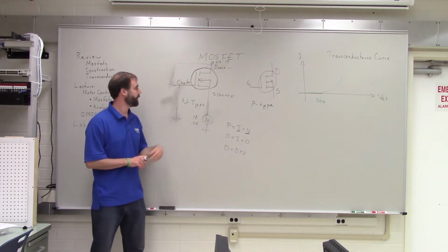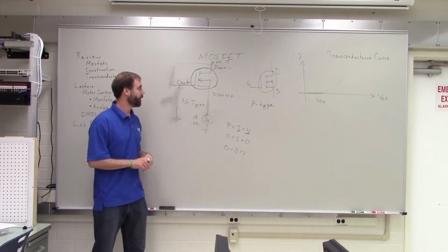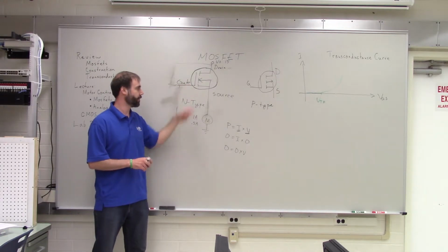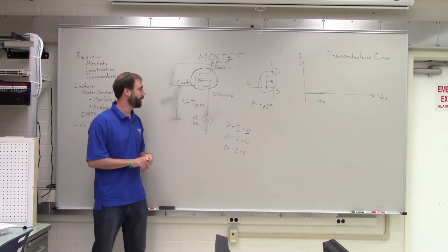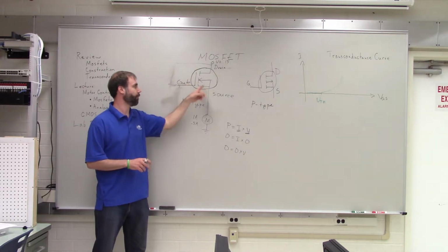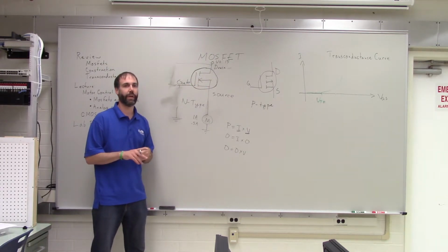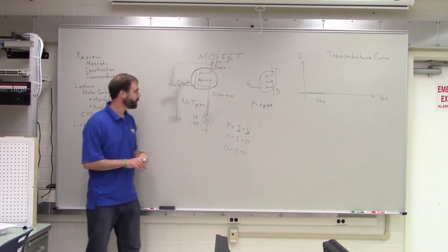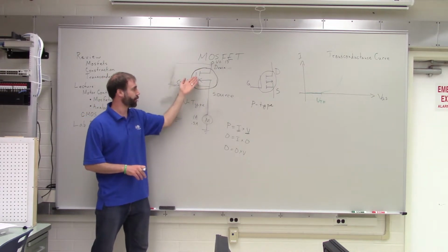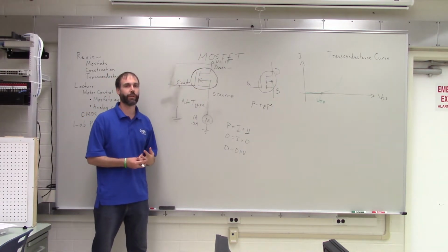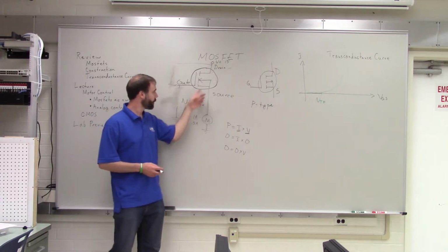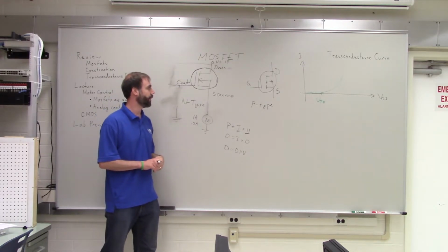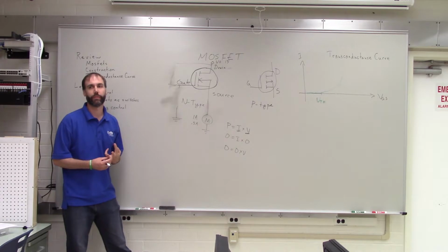The second thing is that a lot of heat inside of electronics is usually a bad thing, right? If it gets too hot, it can start melting things. Even if it doesn't get too hot, you have to put big fins on there or something in order to dissipate that heat and move it away from the device. So you're wasting energy and you're turning it into heat, which then you have to cope with as well. So turning the gate on halfway is something that would work, but is very inefficient. Does that make sense?